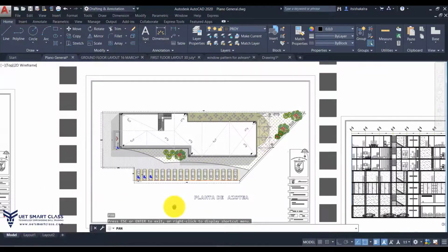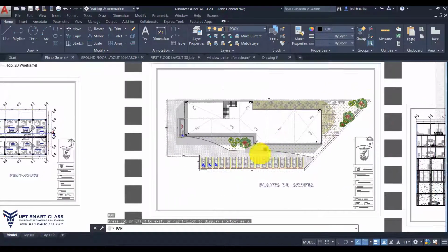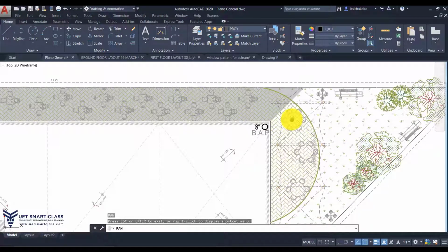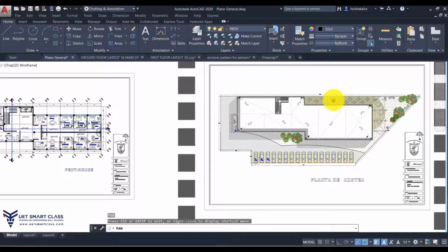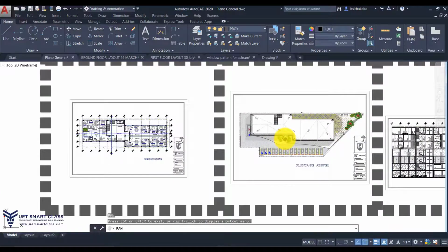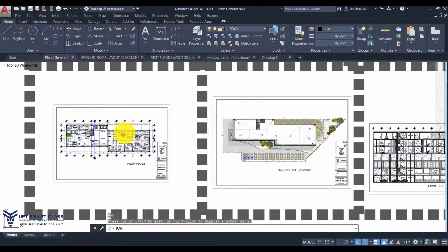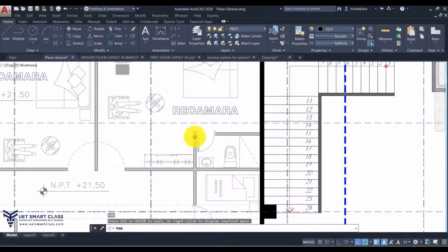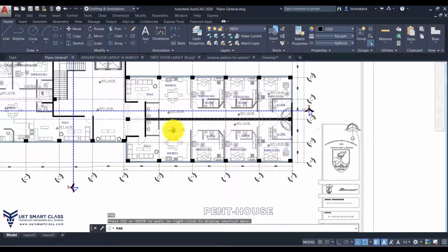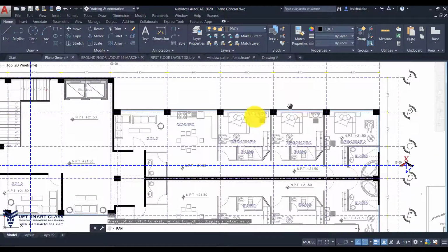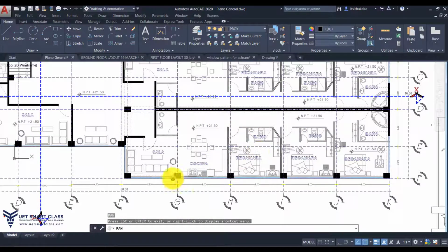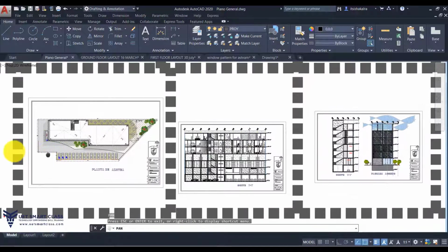So you can create elevations, then you can create different layouts wherein again you can show the landscaping part. You can use different tools for line types, I would say line type, line weight, to show the difference between the objects which are to be shown and the objects which are to be hidden, or the object which has more height and which has low height. So you can separate it. You can detail each and every section of your particular flat or a residential area or a tower or a society, anything. Okay, so you can create sections, you can create furniture, detailing.